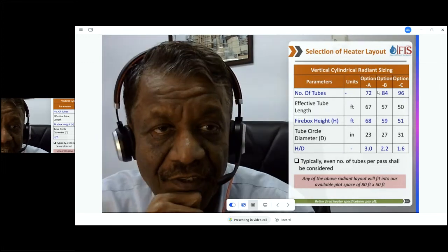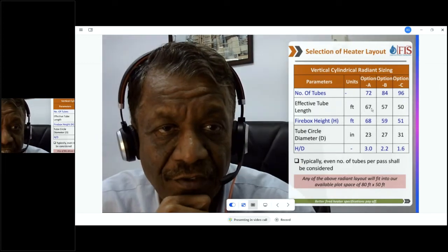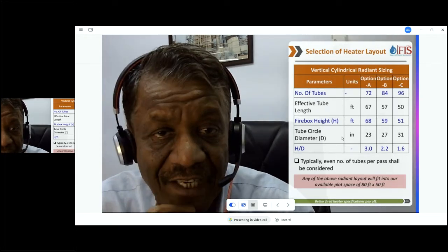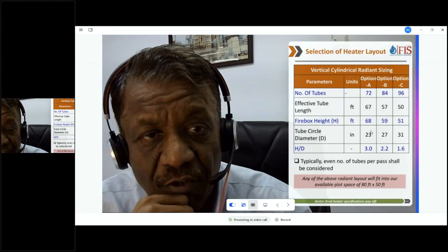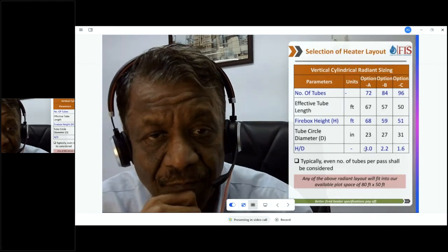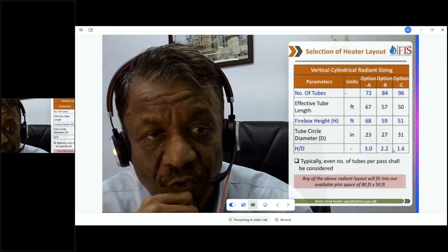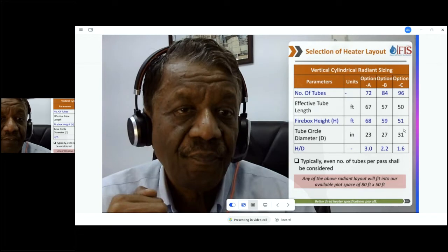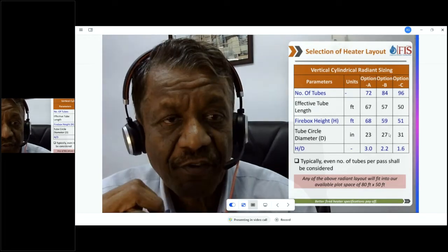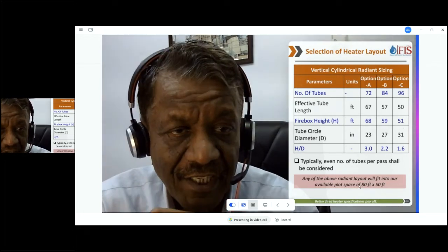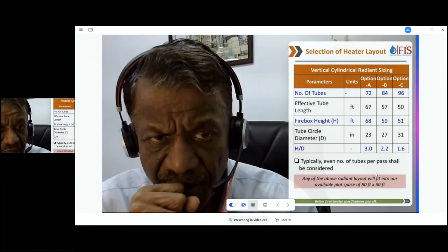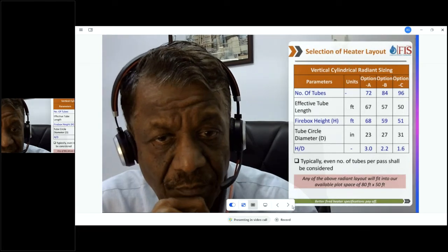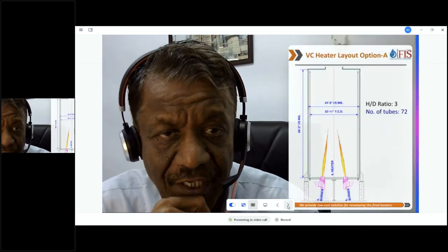When we do that, we get effective tube length of 67, 57 or 50. And we look at the tube circle diameter 23, 27, 31 and H by D of 3, 2.2 or 1.6. So anyway, if we have a tube circle diameter of 23 or 27, I think we can definitely fit it in our plot space of 80 feet by 50 feet. So we move ahead. I will show you what we mean.